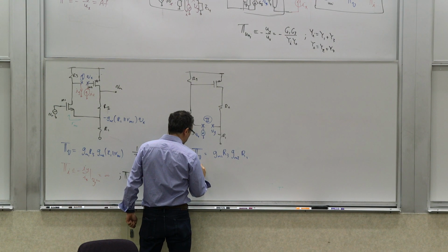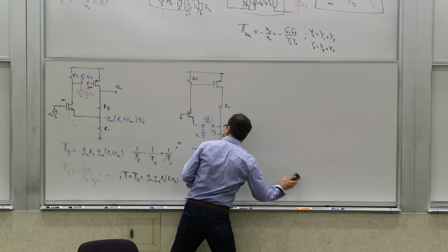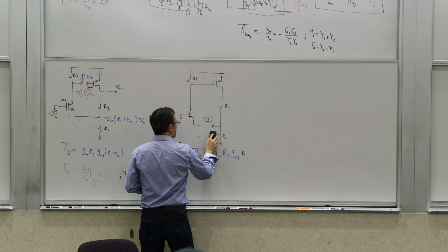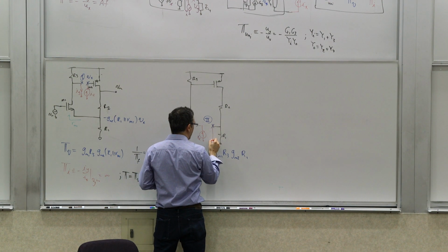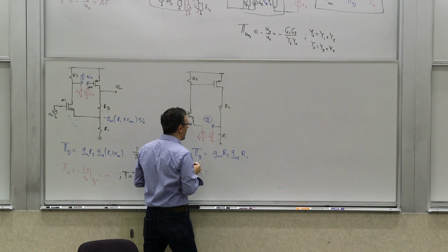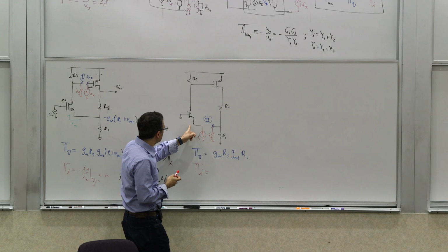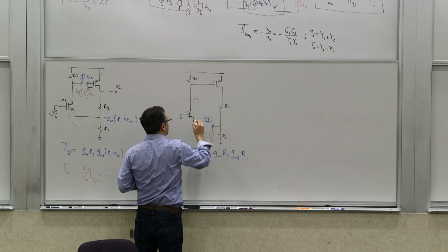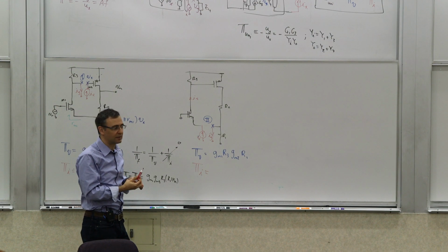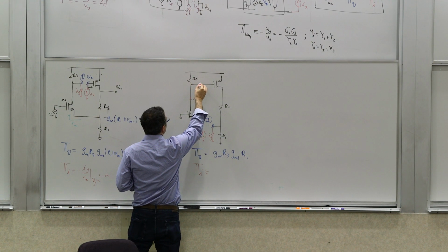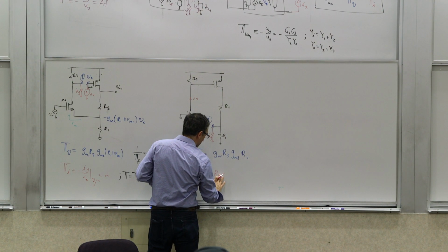So let's calculate the current loop gain. For the current loop gain, we get rid of this, and then we put a current source here, inject Ix, and short circuit and measure Iy. Okay, so if you put Ix through here, Ix is going to go through here, right? The gain for that transistor is 1, low frequency. So this is Ix. So this voltage is going to become Ix times R3. So there's an R3 there, right?